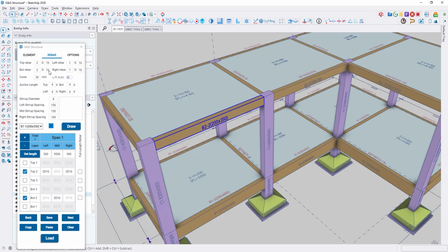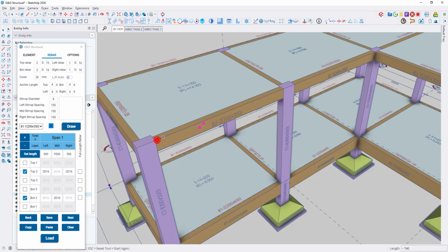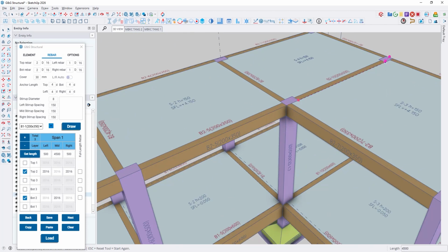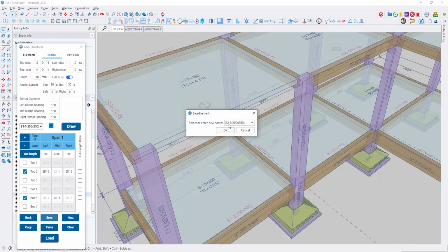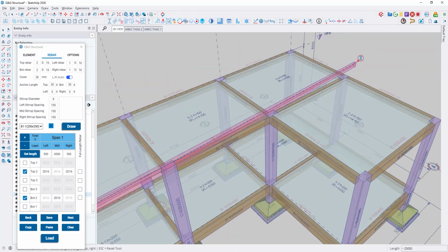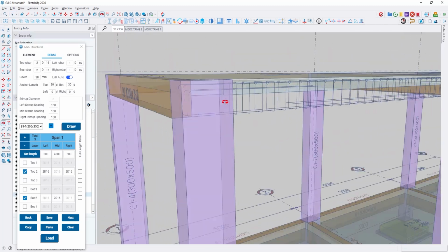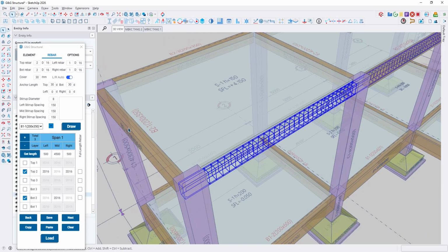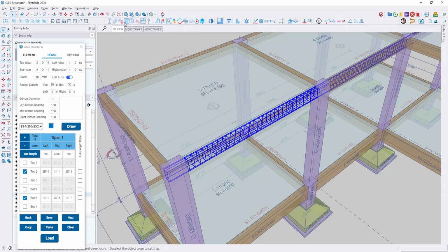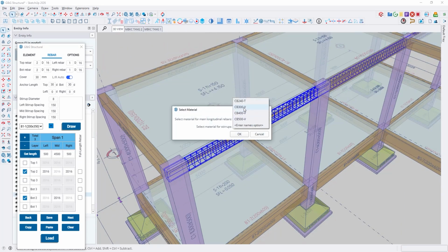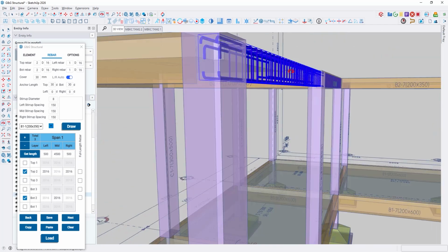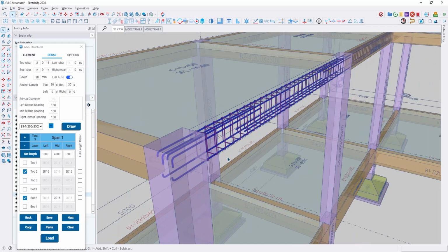Next is the beam reinforcement deployment. The geometric information of the beam is stored in the model. Therefore, we can reload the data, identify span lengths, and save parameters for future editing and updates. Users only need to snap 2 points. The system will automatically arrange the longitudinal reinforcement in the beam according to the preset parameters. When needed, we can switch to 3D rebar display mode for visual inspection in the model.